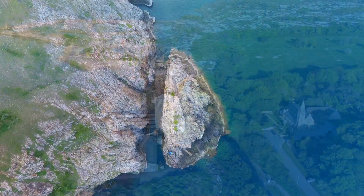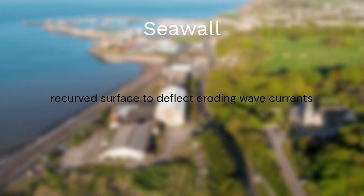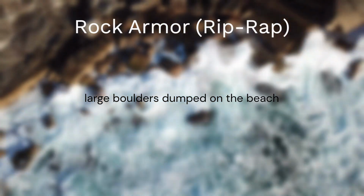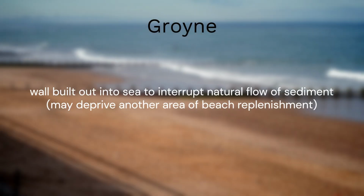To address these, various methods of coastal protection are used. For instance, seawalls deflect wave energy, rock armor, or riprap, protects the shore with large boulders, and groins disrupt sediment movement to prevent beach erosion.